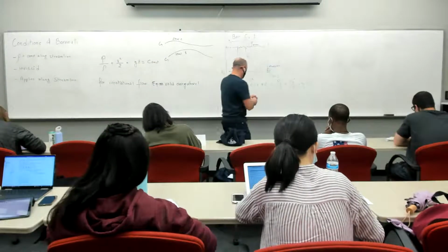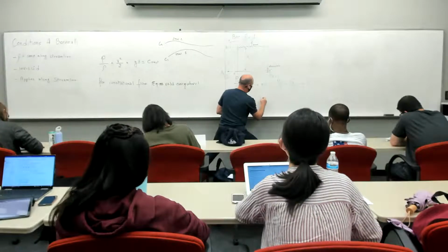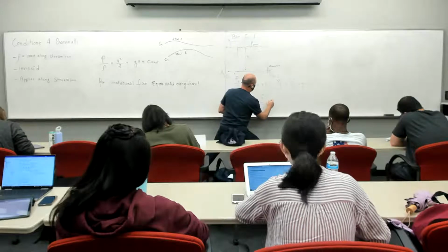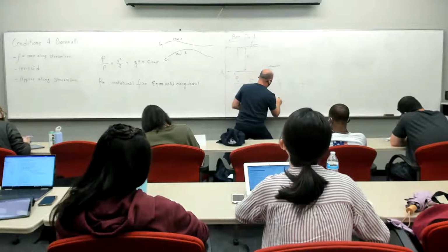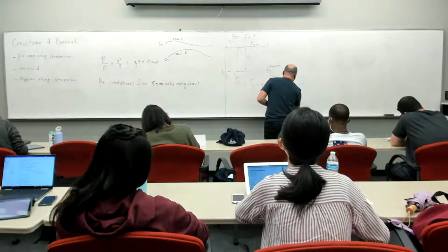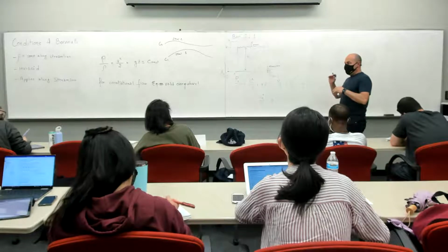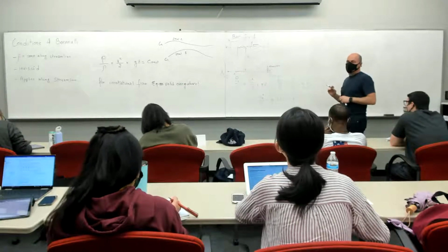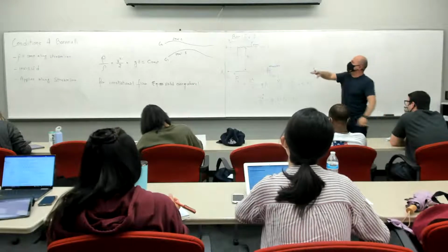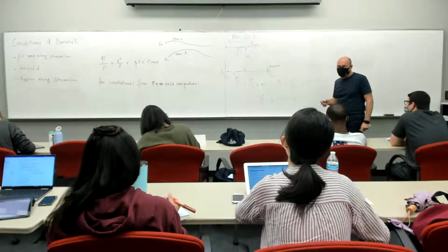Then what we have is V2 squared over 2 equal to g(Z1 minus Z2), which is equal to gH. That's the height of the tank at that point. Now H is going to change with time eventually, but suppose that there's a river that's filling the reservoir constantly.